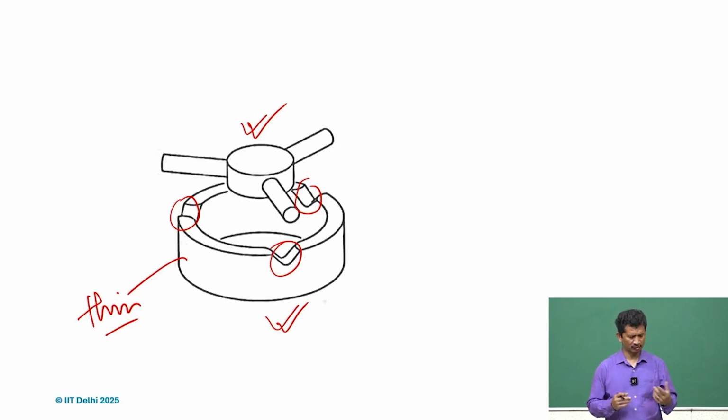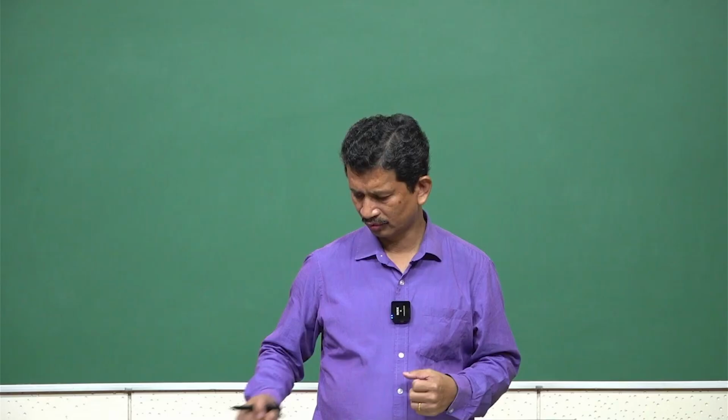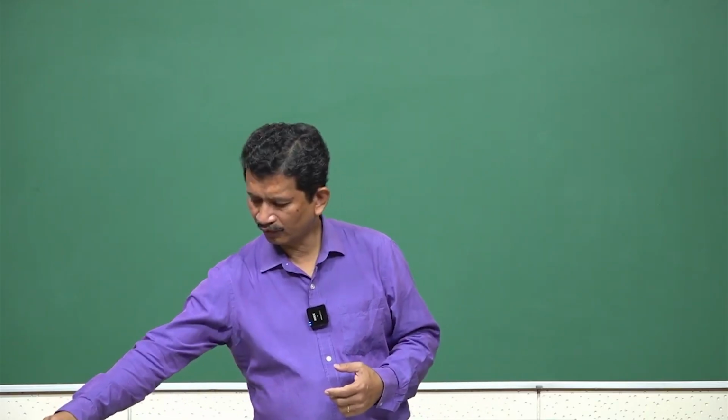Whether we can use this systematic approach of exact constraint design and get the same results. So, again if we assume that it is a thin tube, there will be two contacts defined here, two contacts defined here, and two contacts defined here. So, it is very similar to what we just discussed. So, three balls in a tetrahedron in three V grooves, and if we have this, then why should it not work? So, we can also see from the example.